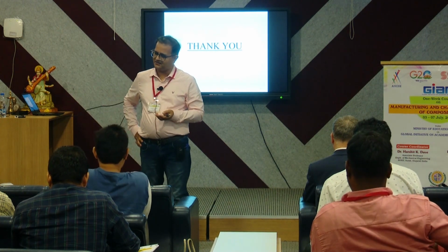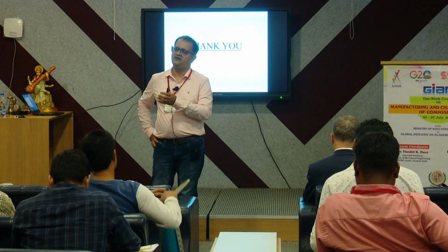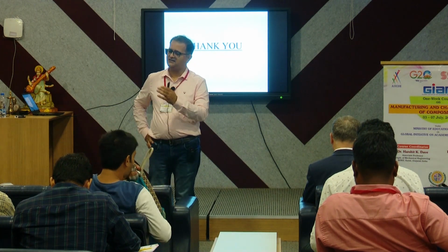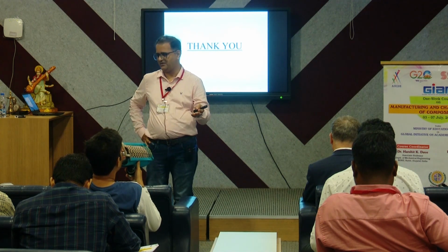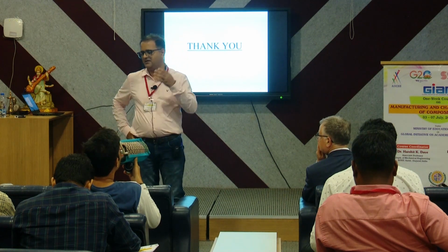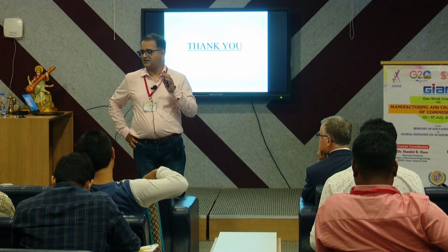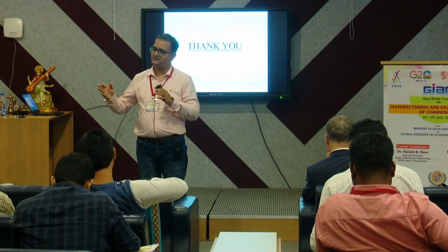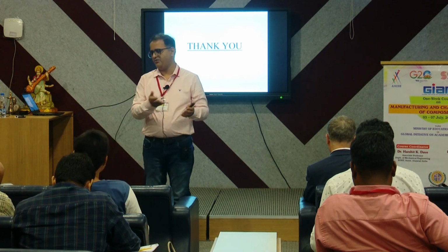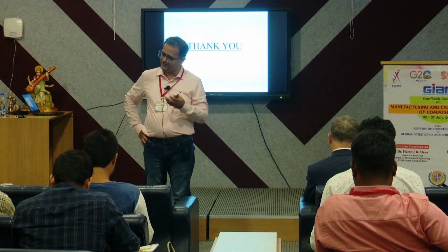Naturally, jute has lesser strength as a fiber, and when you are going for a certain volume fraction with any fiber, the resin has a lesser contribution to the strength as compared to the fiber. Because carbon fiber has the best possible strength as an individual entity, and considering that the resins and volume fractions were the same, carbon fiber gave better results as compared to the jute one. Any natural fiber you take, man-made fiber will give you better strength.